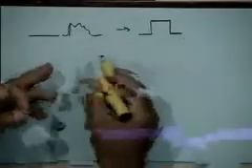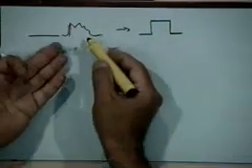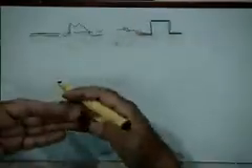And if you are able to do that, you will eventually get a clean signal, right? And that is how you are able to reduce noise in digital communication. And that's the essence of trading bandwidth for noise once again, because bandwidth will increase because you are transmitting pulses rather than continuous time signals. However, it's clear that you cannot do this with analog transmission, right? You can't carry out such a cleaning operation for an analog message, because there is no way to separate the two. There is no way to convert that into something else.